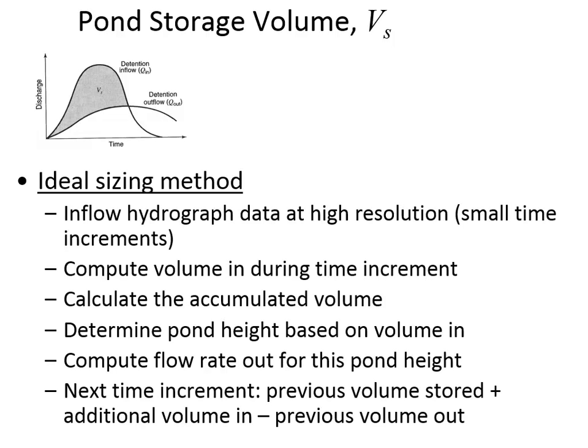So the process that we're going to follow to size the pond is, in a best case scenario, we'll have an inflow hydrograph that tells us how much water is coming in at certain times during the storm. So we'll have an inflow hydrograph, and then we'll calculate the volume in during the time increment, and that's going to feel very familiar to you. You're going to be saying the volume that came in was the flow rate during the period times 3,600 seconds per hour, so that's the volume in.